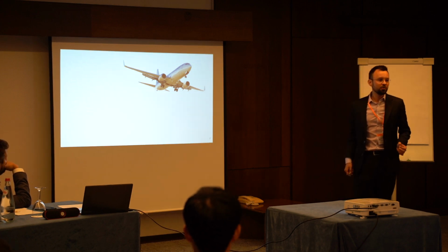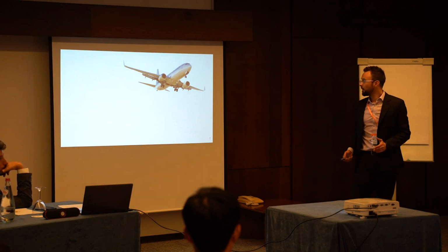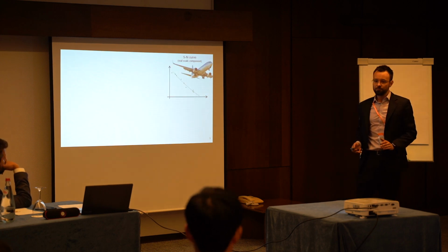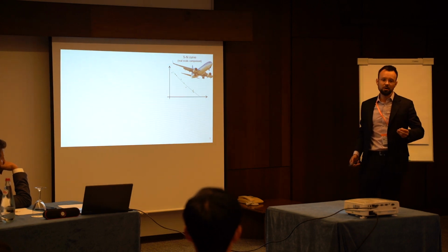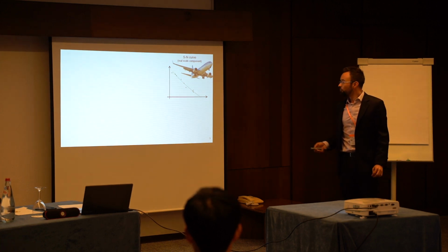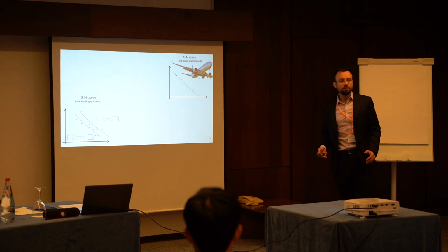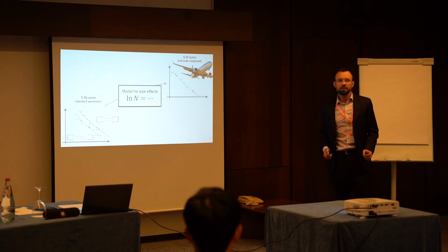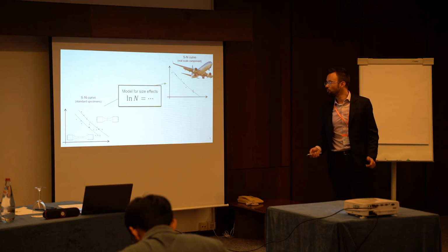As engineers, you usually need to perform fatigue tests of real scale components. We are interested in the SN curve. A common approach, however, is very costly and can also be time consuming. Then a common approach is to replace the real components by standard small specimens. And the fatigue results can be extrapolated by an empirical model or a statistical model.